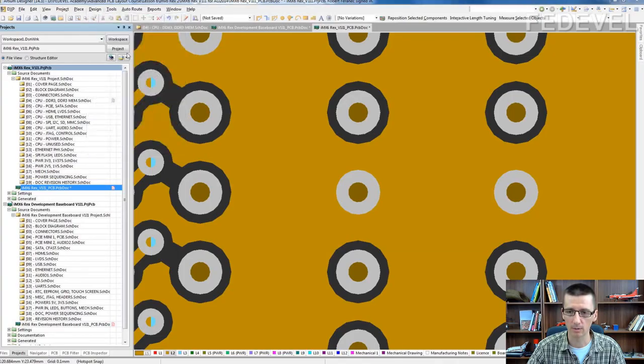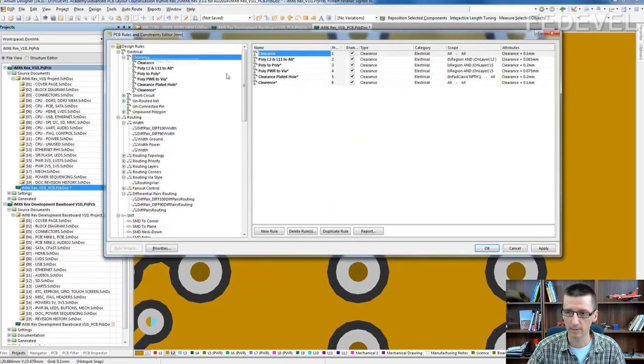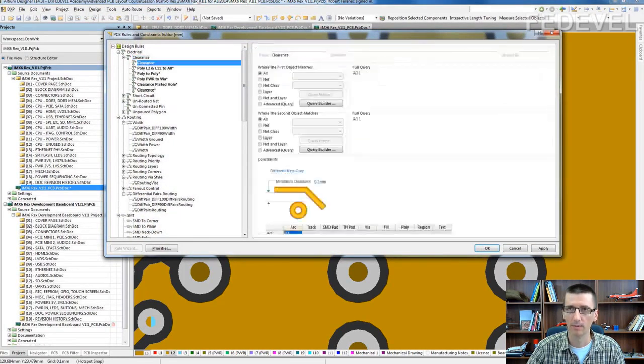Go to Design, Rules, Clearance, New Rule, double click, and it will be like this.